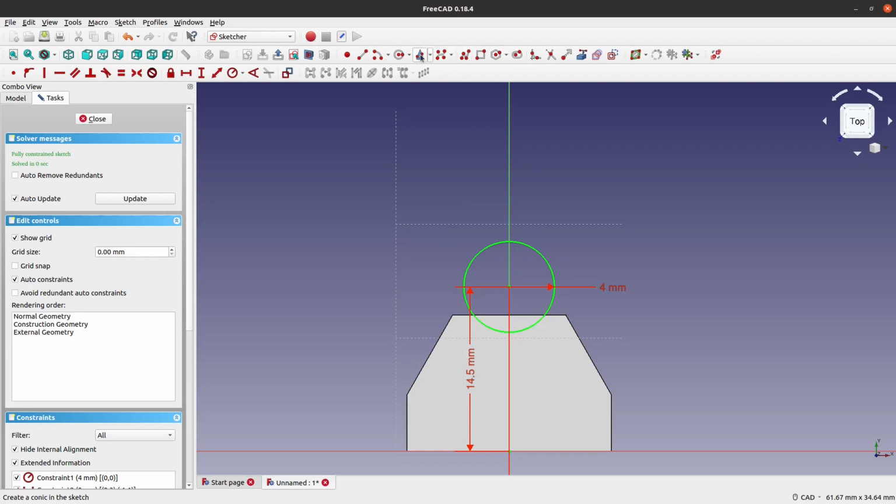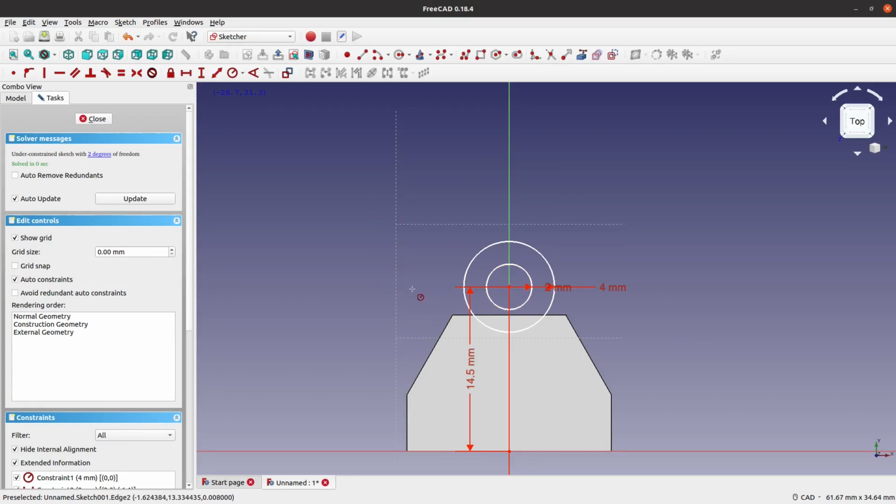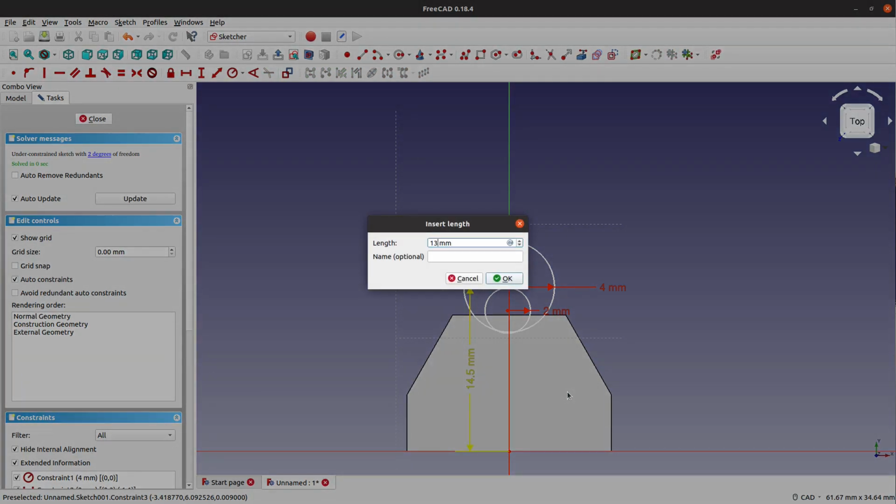And then I'm going to draw another circle just to get an idea of how this will look when I hollow out the stem. So I'll actually be deleting this circle later, but for now I'll just set this to 2 millimeters, and we can see how it fits against the traffic light, and it needs to be further down because that's not going to allow the wires to go into the back of the thing. So that's actually the sort of position I want there. This is about where I want the hole, so that will allow the wires to be fed into the back of the traffic light. I can move the larger circle down to 13 millimeters.